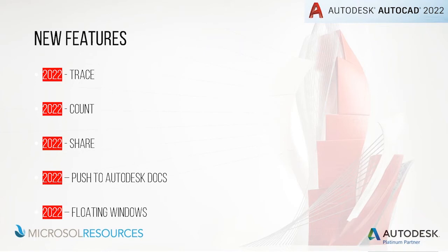So there's a general shift towards that, where no matter where you are, as long as you have an internet connection, you should be able to access AutoCAD. So that's very neat. And just to list off some of these new features, we've got Trace, which is a markup tool that helps with collaboration. We've got Count, which basically aggregates all of the objects within your drawing, so you can quickly and easily see how many blocks of a certain type are in the drawing, things like that.